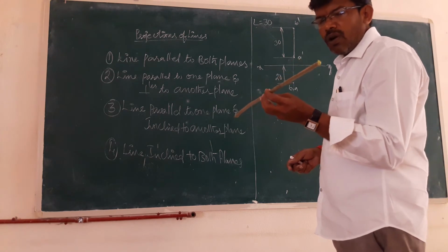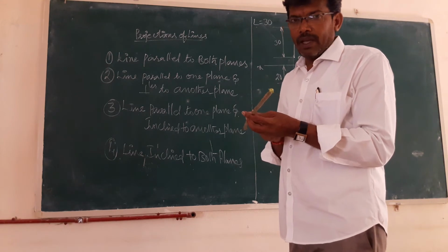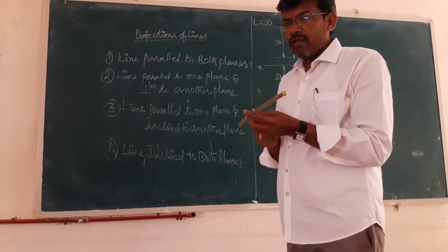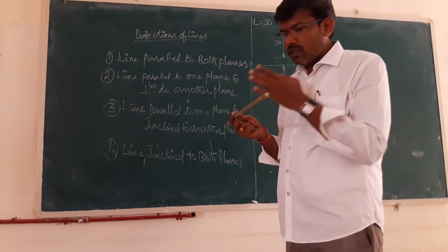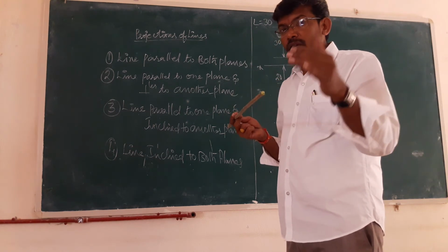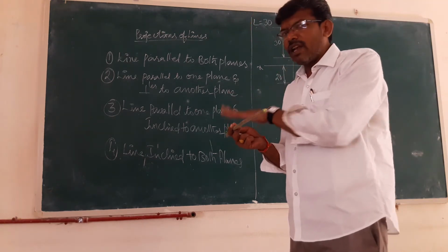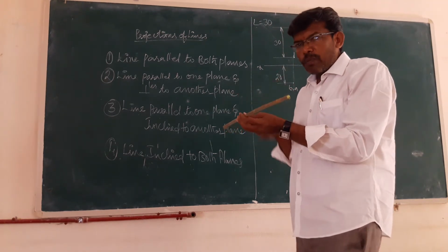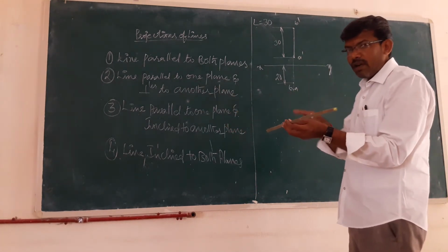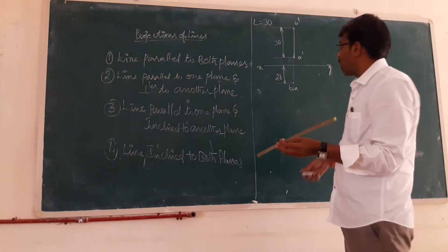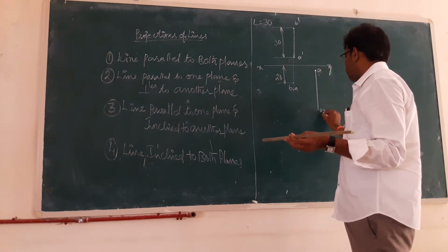Okay, then now in which view you have to concentrate, in which view can you observe the true length of the line? Now you are seeing from the front, so you will look at only one single point, right? The length of the line, which is 30, you cannot see in the front view, so when you look from the top position, then you can observe the full length of the line, such that the top view is going to be drawn first in case of the orthographic projection. So now I will write down this point is A and this point is B.